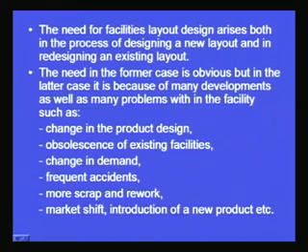Then the frequent accidents. Sometimes it may so happen that there are accidents because of certain layout problems. In order to overcome that kind of scenario, we may plan to redesign the layout. Then more scrap and rework. Sometimes the layout is such that there is a lot of rework and scrap resulting out of that layout problem. Then we may think of redesigning the layout. Market shift, introduction of new product, etc. So all these important points guide us that we should now think of redesigning the layout.